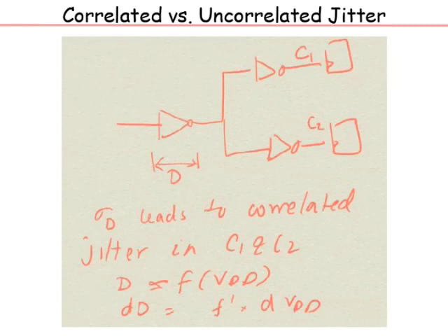Now why is this jitter happening? You have basically two components to the clock distribution. There is the clock source, and then there is the clock distribution network. The clock source itself could have a jitter. That jitter turns out to be usually quite small. But the clock edges are moving through these paths, and whenever there is a fluctuation of the delay, you will have a jitter.